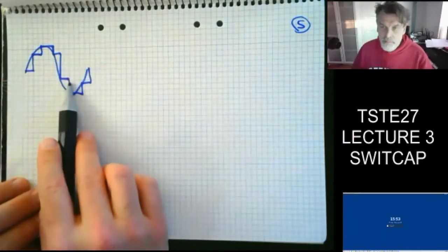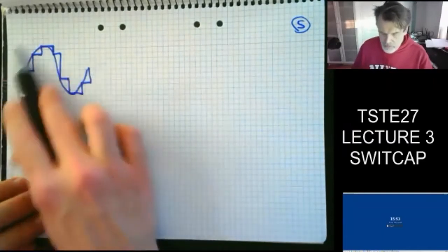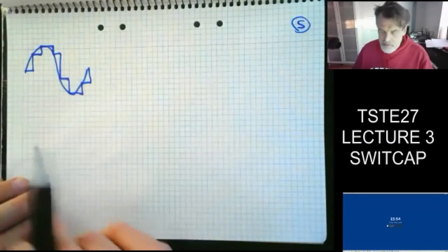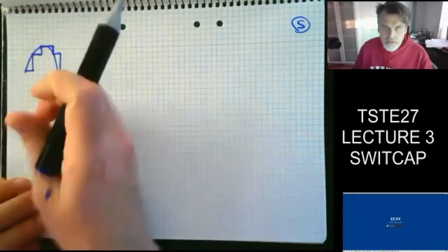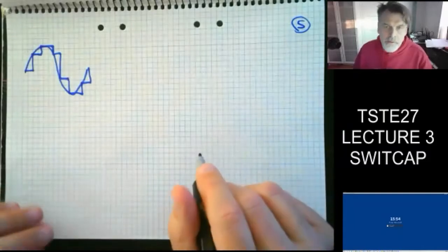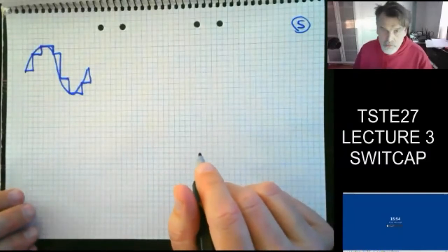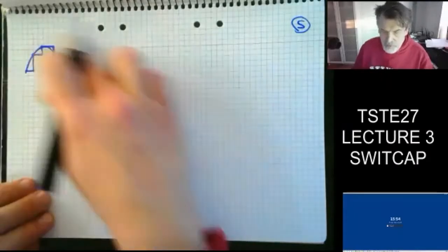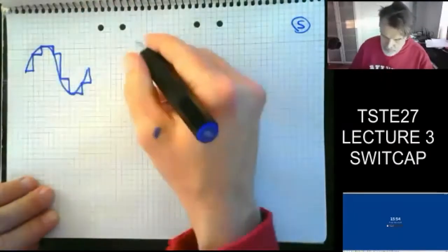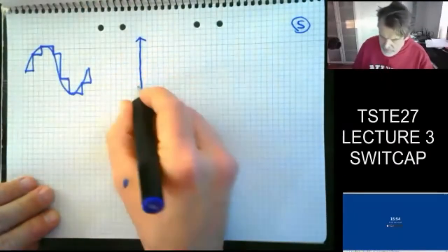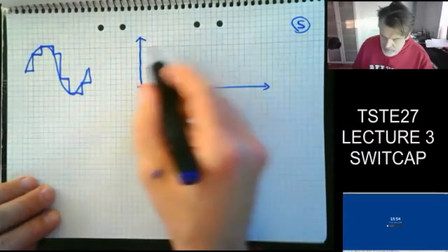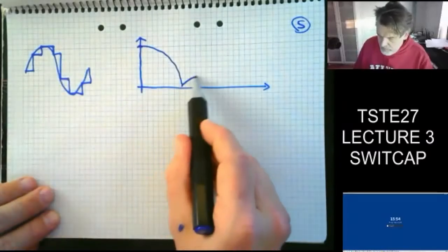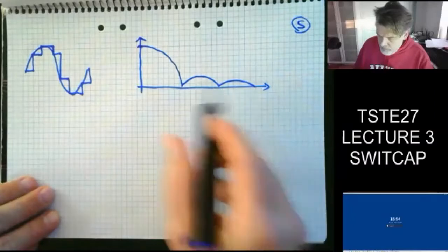And what does this imply, sampling? Well, I don't really destroy the signal. I just sample it in the time domain. So I don't discretize it like an analog to digital converter would do, so I don't add any quantization noise. I just do something with the frequency spectrum. And what's happening is typically that, due to the sampling and sample and hold operation, I get some sort of sinc behavior like this.